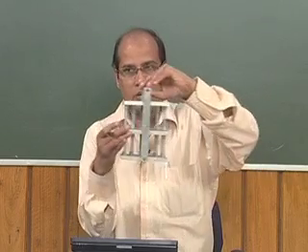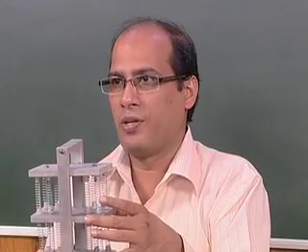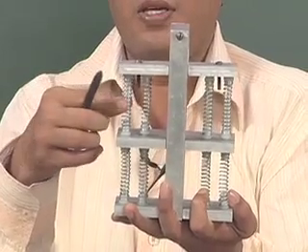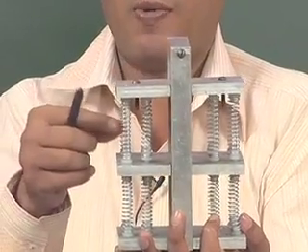So, already we have studied about the 2 degrees of freedom system. This is the equation for single degree, and you have studied the equation for 2 degree of freedom system, and you know the principle of vibration isolation also. So, in case of the principle of vibration isolation, let this be the primary system. To attenuate the vibration of this primary system, you can add another spring and mass system to this system. So, you have to take the spring and mass in such a way that the excitation frequency should be equal to root over K2 by M2.